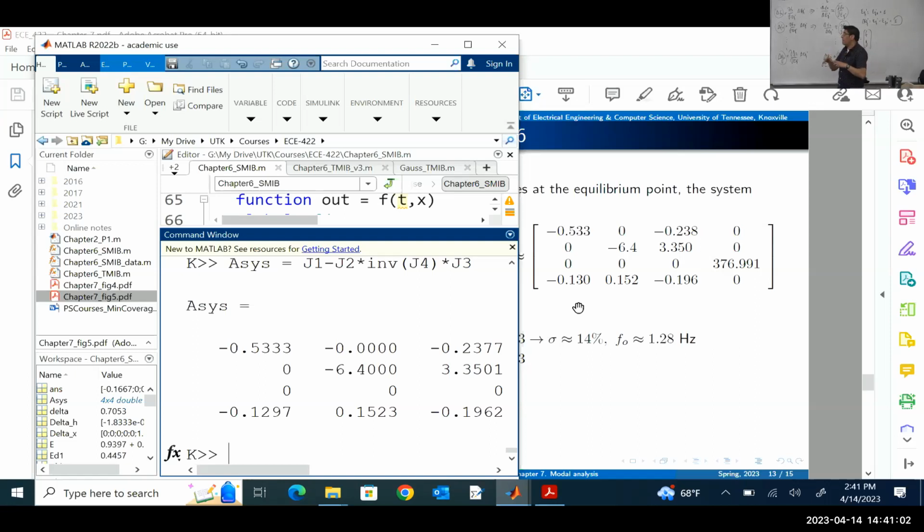And no, because we are trying to build the Jacobian matrix. So we are going to start one variable at a time. If you pick the first variable, as I explained here, you obtain with this procedure the first column of the Jacobian. But then you will go to the second variable, ED prime. Then you are going to pick x0 and increase by an epsilon just the second variable, ED prime. With that new value, you will calculate how much the function will deviate divided by the epsilon, and you will get the second column of the Jacobian. And you will repeat in that fashion until the very last variable, and you will get this large Jacobian matrix.